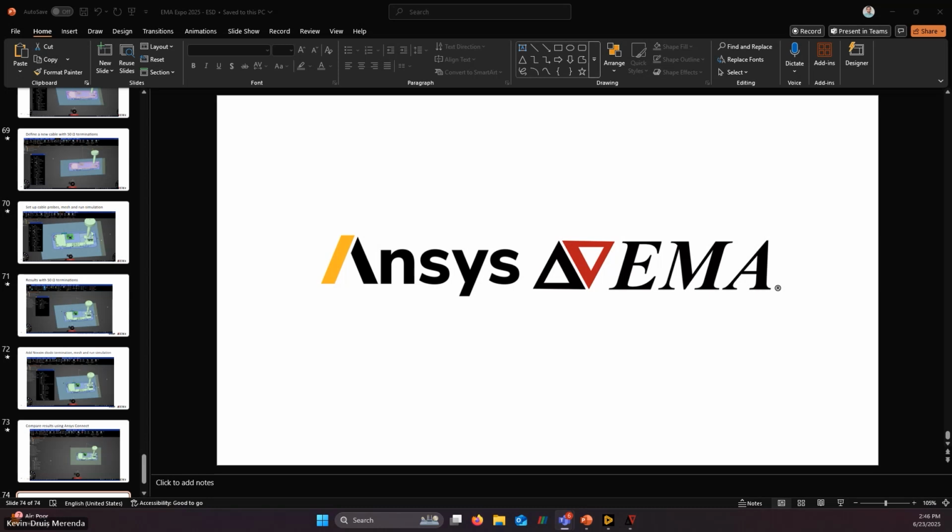Great. Moving on to the next question, also from John. He said, with the 2D simulations, can a particle source be implemented for an internal ESD type simulation, or are only voltage/current sources supported? Yeah, you can, even with 2D simulations, you can use G4 for charging the dielectric. I think that's what the question is there.